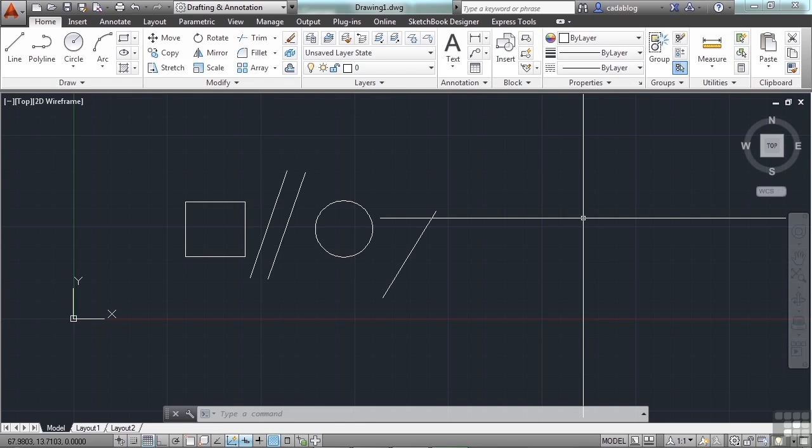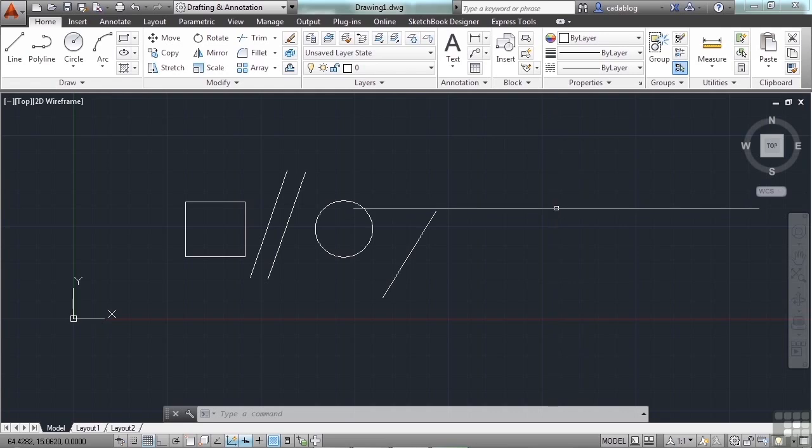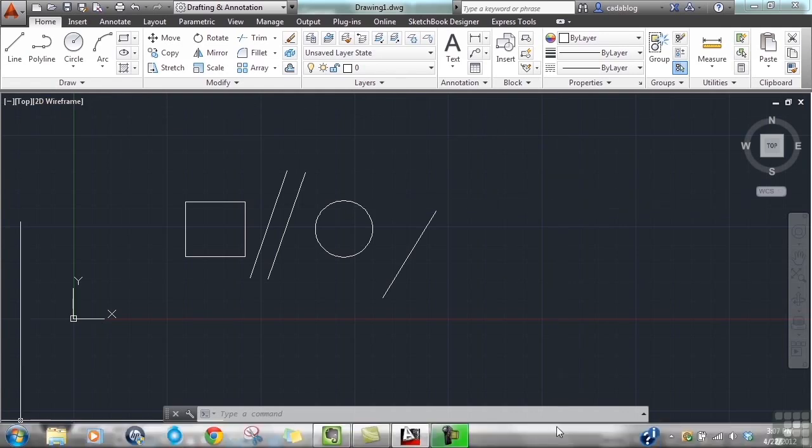The crosshairs consist of 3 major items: your vertical line, your horizontal line, and the pick box. These 3 items are there for visual reference. The 2 lines are perfectly straight and they intersect at the middle of the pick box. This point of intersection is the point where you will select objects or insert new objects. We mentioned that earlier. When you move your crosshairs off of the drawing area, which is this big box right here,